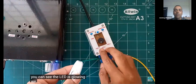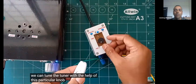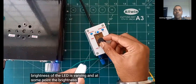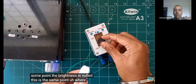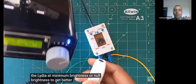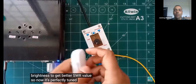We can tune the tuner with the help of this particular knob. And while tuning, we can see that the brightness of the LED is varying, and at some point the brightness is null. This is the same point where the SWR is minimum. So we have to keep the LED at minimum brightness or null brightness to get a better SWR value. So now it's perfectly tuned at 14 MHz.